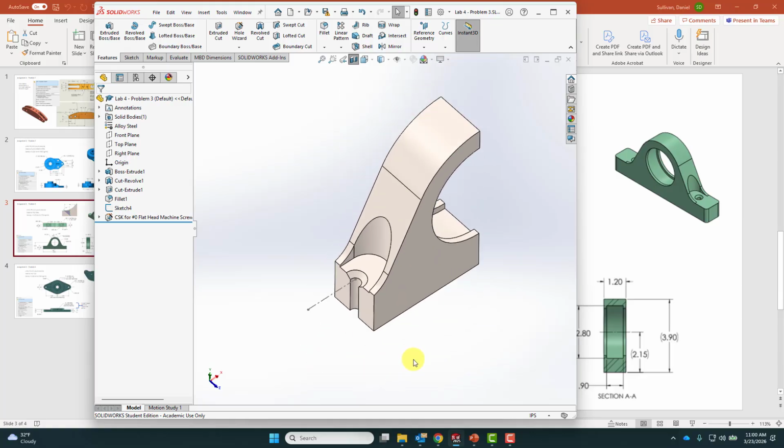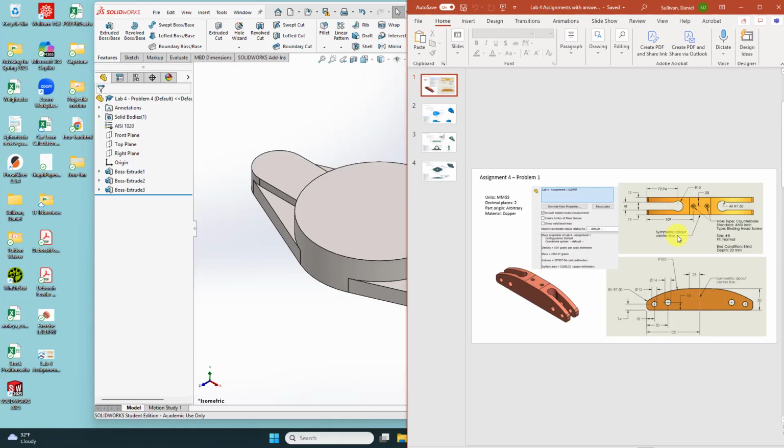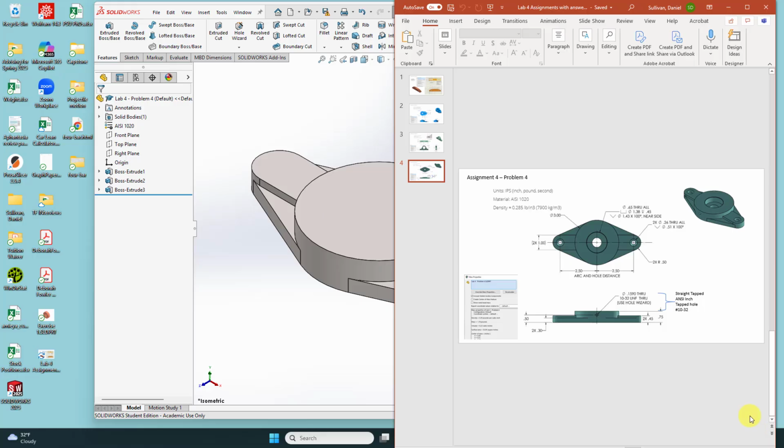Okay, and we'll do one more example here, one with a counterbore. So let me pull that up. For this part here, we're using the Hole Wizard to do three things. There is a countersunk hole here, there is a threaded hole here, and this big cutout here is actually given to us in terms of a counterbored hole. So I can use the Hole Wizard for all three of these situations. So let me just bring this in here and use my zoom tool here.